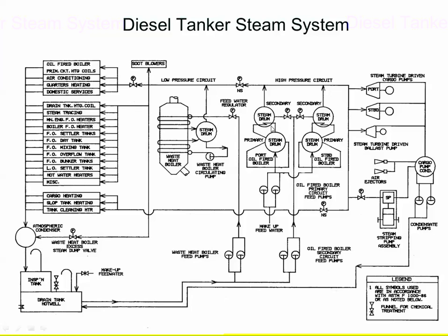There are no leaks in this system, which means I don't need a feed pump, and I don't have one. I have makeup feed pumps where I could add water initially to get the drum at the mid-level, and slowly over time, if I did have some leakage, I could put a little bit more water in. But I want you to understand that in normal operation, there is no feed pump on this system. It's all natural circulation. The gas goes up, changes state, and then flows back.